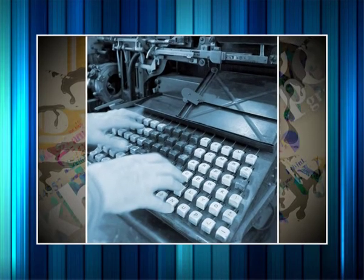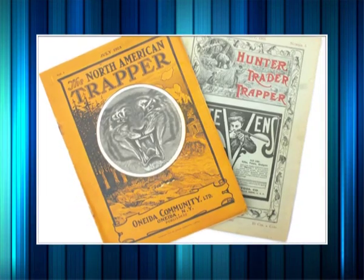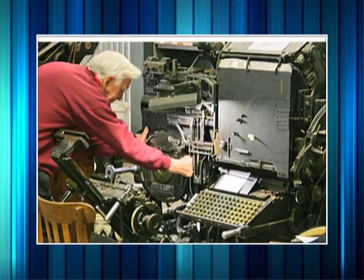When a key on the keyboard is depressed, metal matrices with recessed images of individual characters drop from the magazines. Expandable space bands are set between the words. A line of text is formed from the matrices and bands and then sent to the caster. All subsequent operations in the machine are done automatically. The hot type metal fills all the recessed images of the characters on the matrices and upon cooling forms a solid line with a raised printing surface. The cooled line is ejected from the mold, given fine trimming for height of type and point, and placed on a receiving table.